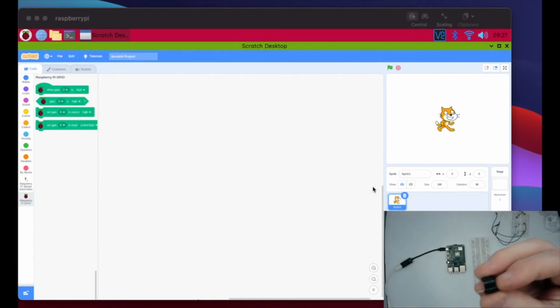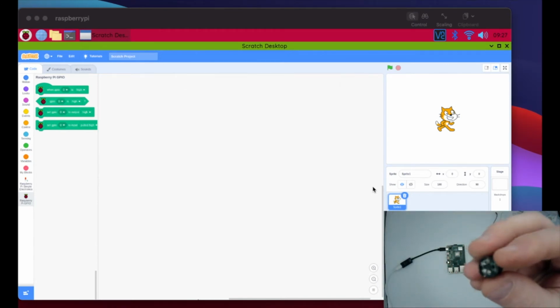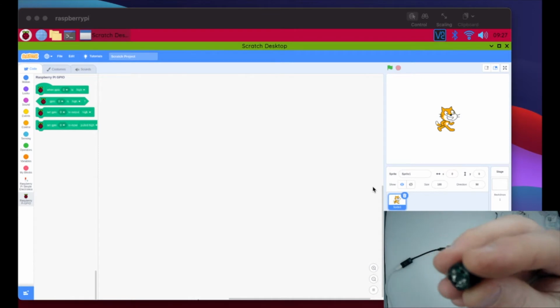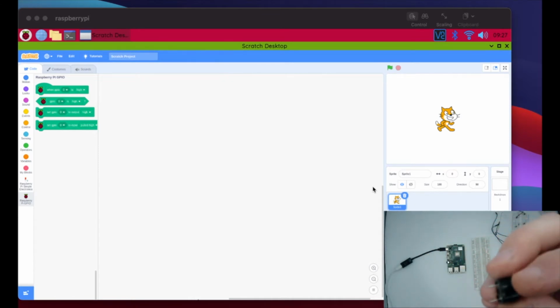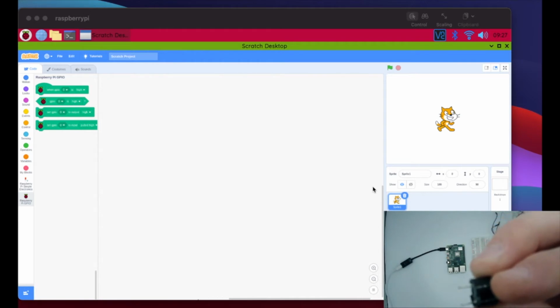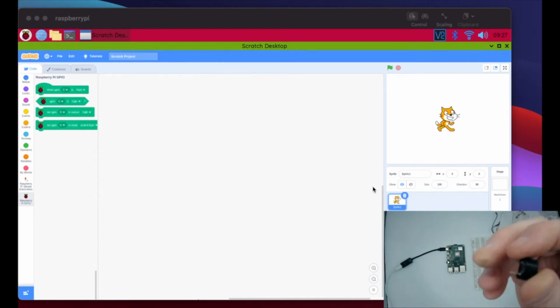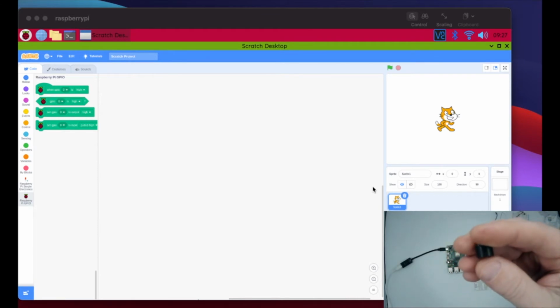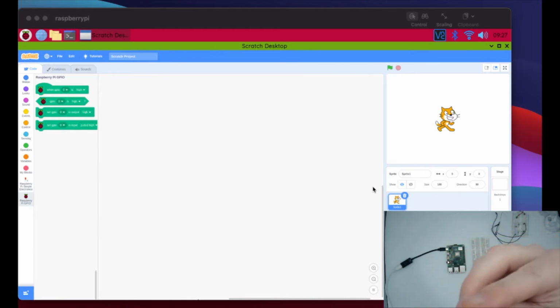Okay, so let's take a look at this little tiny buzzer. It's similar to an LED, and you may run into this sometimes, where if you're looking at mine here, the legs are the same length. But buzzers, for the most part, are just like LEDs. They have to have a positive power supply going to the longer positive leg to work.